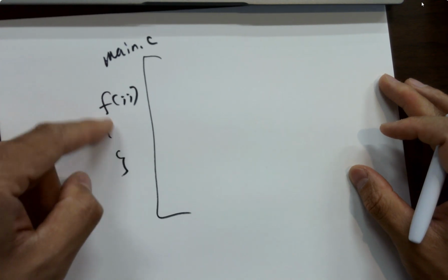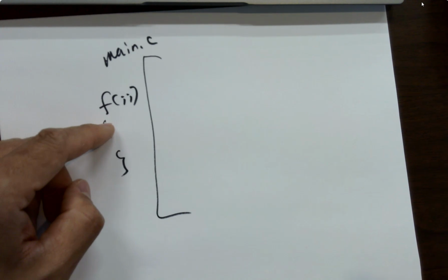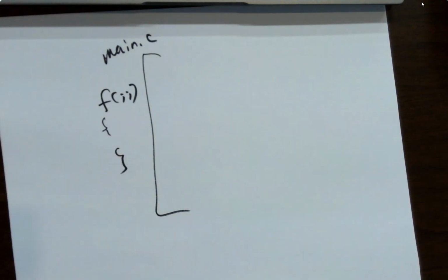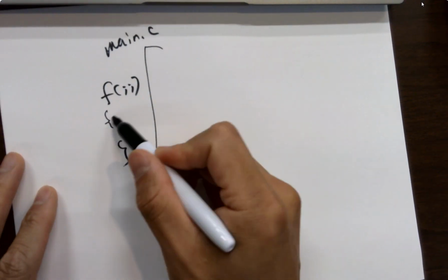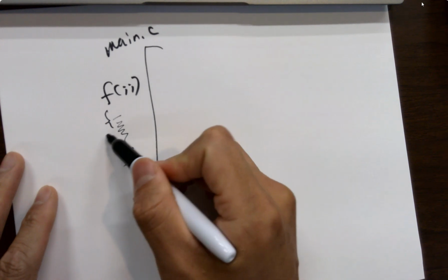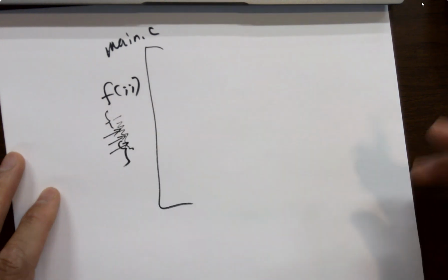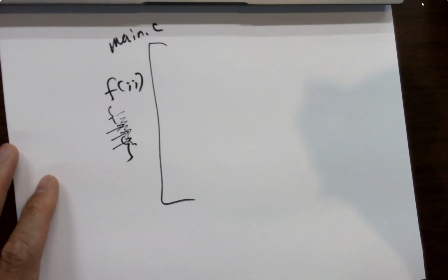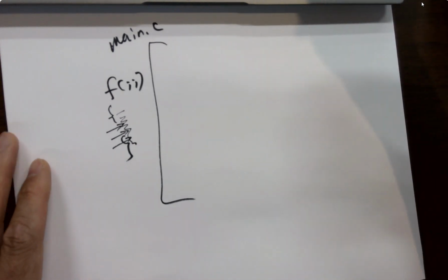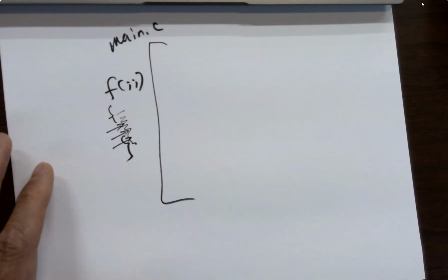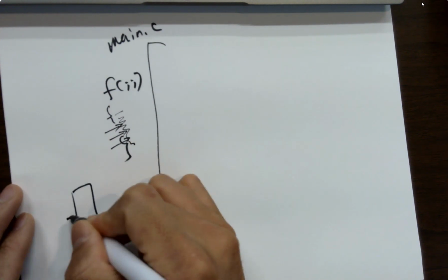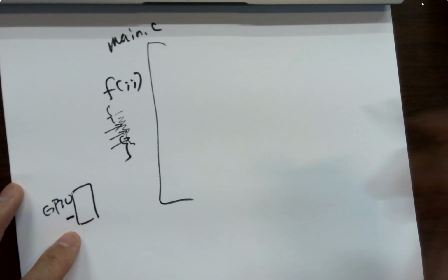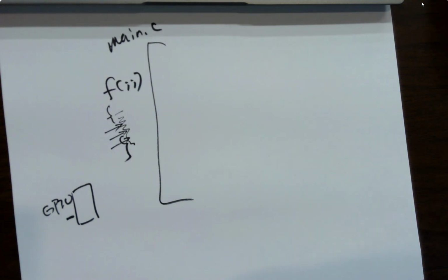So your microcontroller may only have one loop, and cannot respond to anything else happening outside in the world. If you have an interrupt, no matter what is happening here, it's going to interrupt it here, or here, doesn't matter. You can use a timer to trigger an interrupt. You can also use an external trigger. For example, someone presses a key. It senses that key from that digital pin, the GPIO, and triggers the interrupt to run your interrupt routine, a specific function in the program.